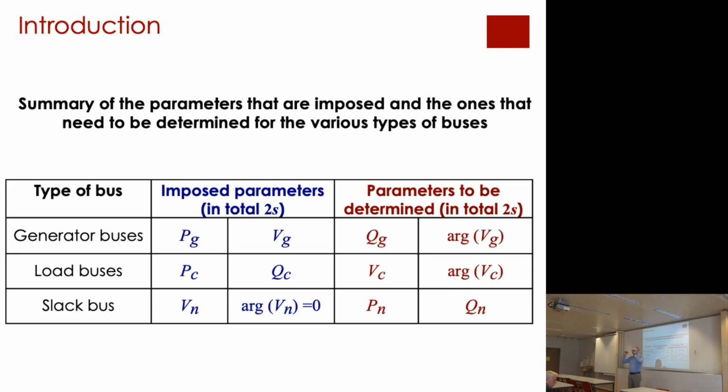Of course, due to operational considerations, you can slightly move the V, because you know that by increasing the V in a given node, you have beneficial effects for the rest of the grid. But still, it has to be constrained within the bounds of the voltage that are acceptable for the system. If in your solution you get voltages in the loads that are outside plus minus 10% of the rated value of the voltage, the solution that you get is technically unfeasible. It is an equilibrium of the system, because you determined the equilibrium of the system. However, technically speaking, you cannot deploy this solution because you are outside the operational bounds of the system. Okay.